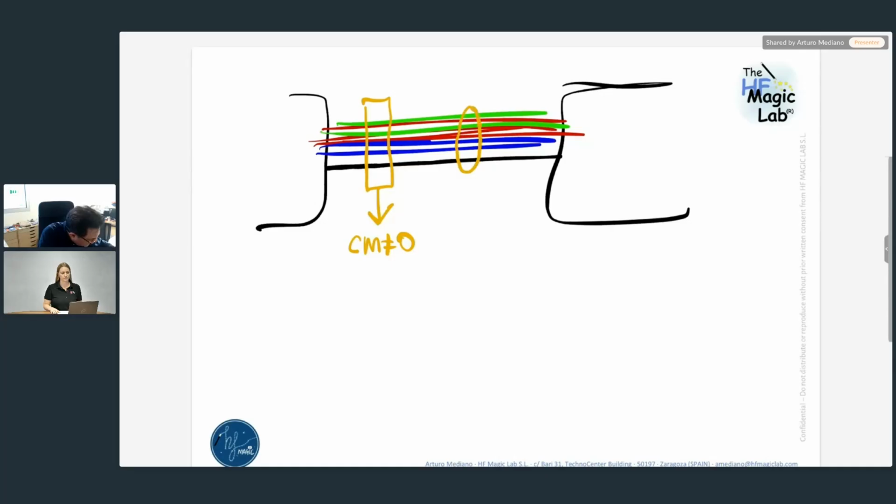So you will need to filter all of them with series impedance, including the ground signal. This is the only possibility to reduce the problem. Depending on the frequency range, perhaps you can introduce a ferrite in series, or perhaps you introduce in your PCB small ferrite beads in series with each line. Remember that introducing impedance in the ground wire is not always a good strategy.